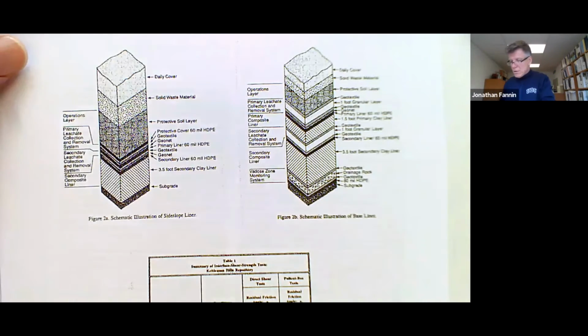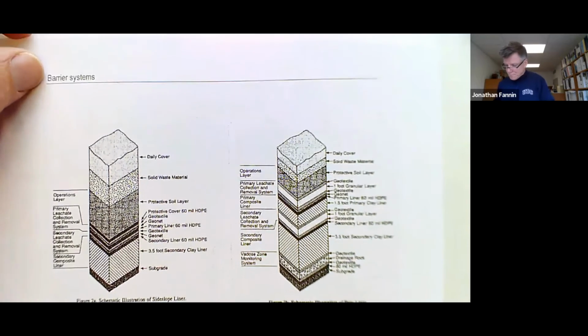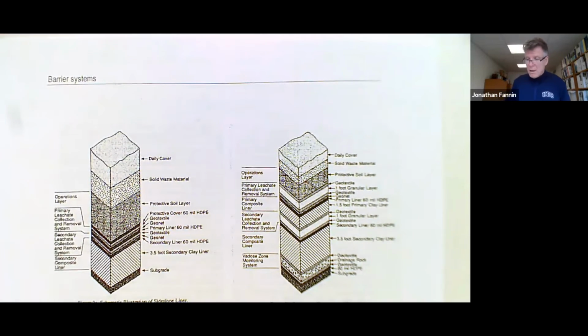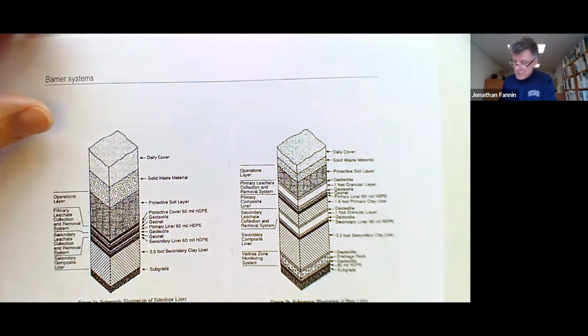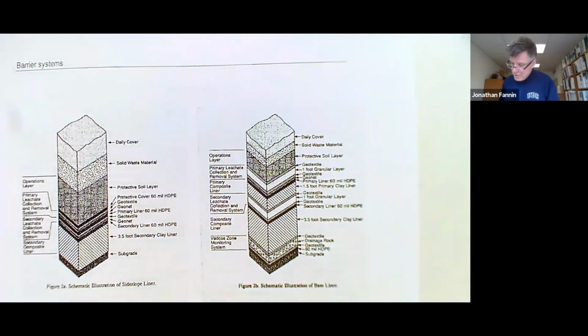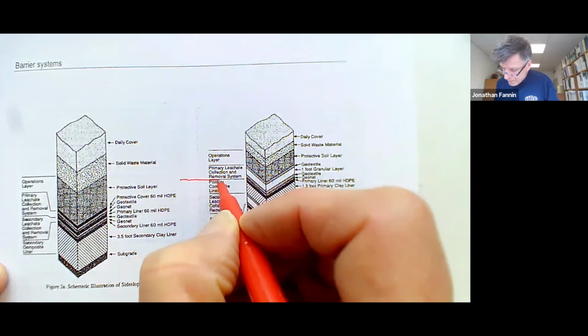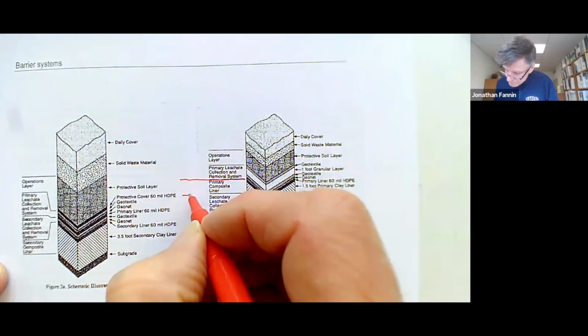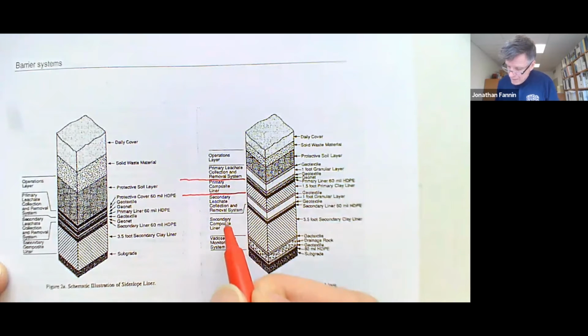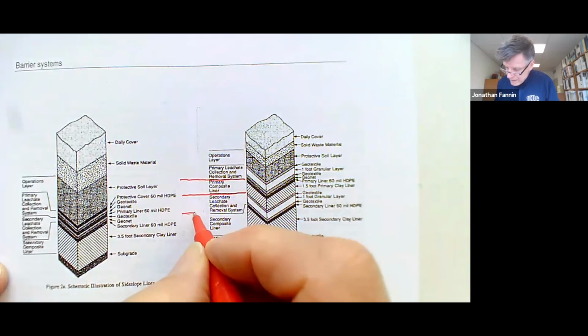And then if we move to look at Kettleman Hills, we discover, my goodness me, we can have quite the combination of materials by drain, barrier, and what those individual components of the system are made from in terms of materials. So let's just flag to carry it through. There is that primary liner. There's a barrier, and there's a secondary liner or secondary barrier.